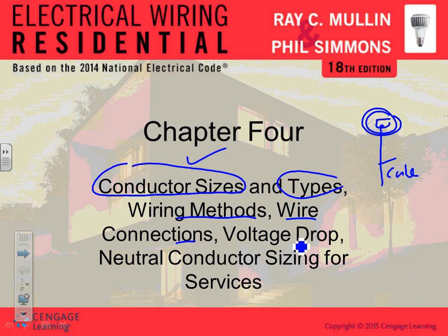So when you tie equipment, guys, you don't just tie them up in the air. You take a cable into a lug. The conductor has to land in a lug. These lugs have to be rated for certain things. We'll talk about this. There's a concept called voltage drop calculation, guys. I don't know if I will be able to do it today, but we will do voltage drop calculation.